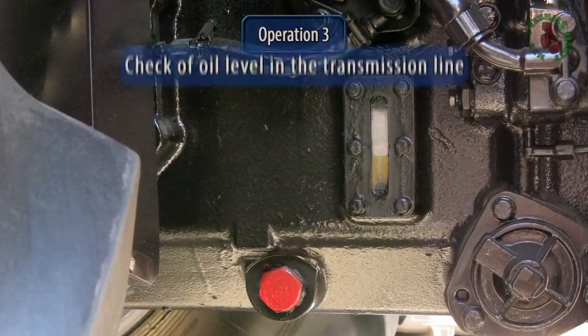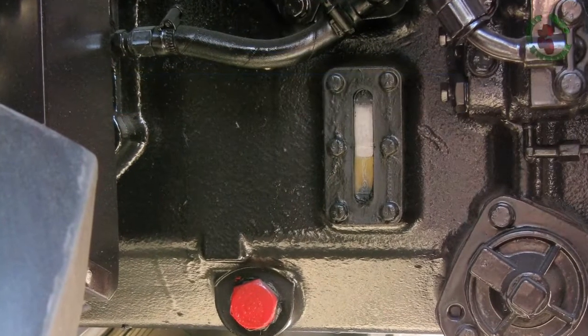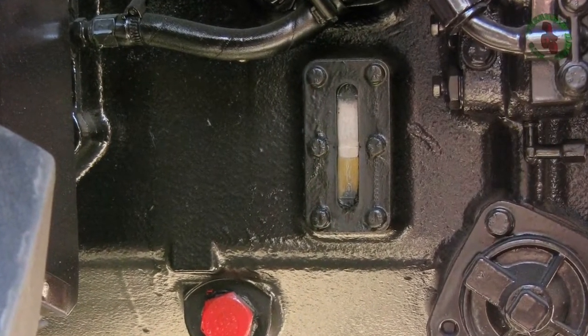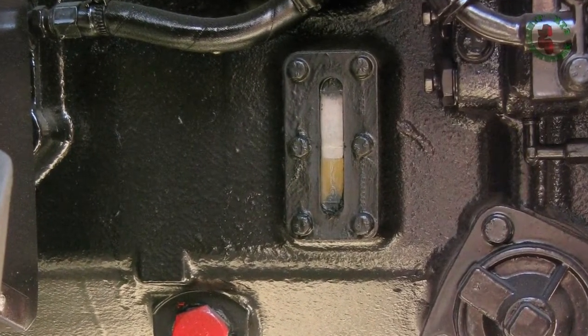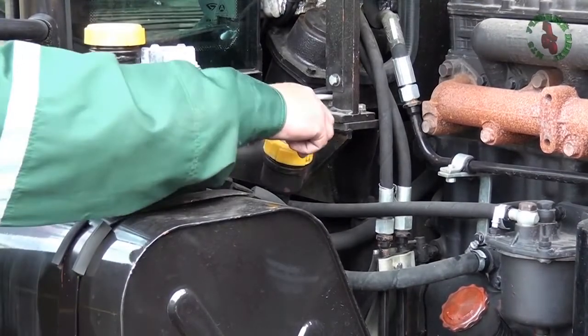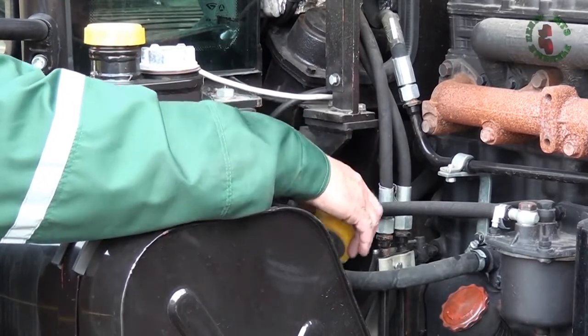Operation 3. Check of oil level in the transmission line. Check the oil level in the transmission line by means of a probe. The oil level shall stay between the probe marks. When necessary, turn off the cap and refill the oil up to the required level through the filler neck.